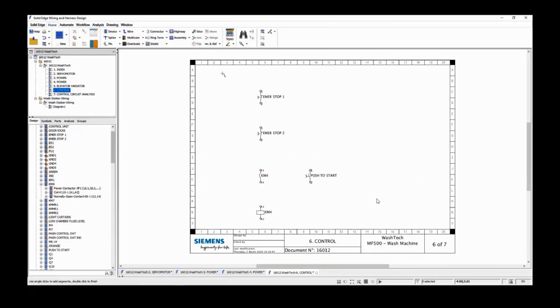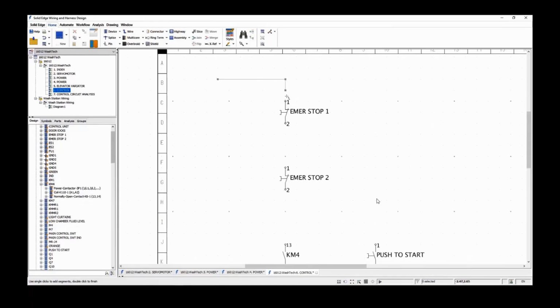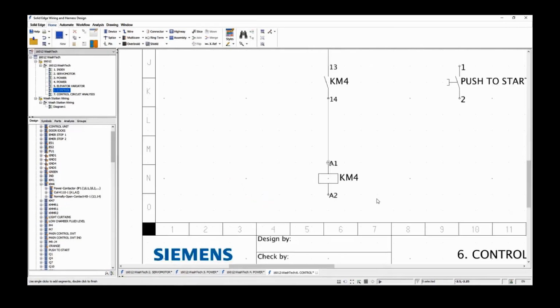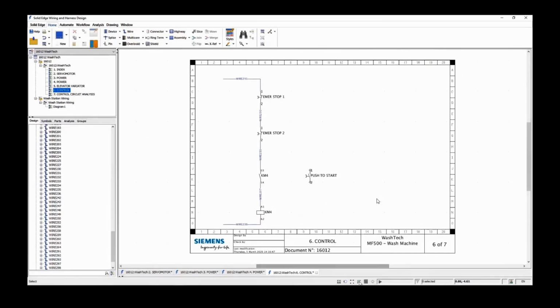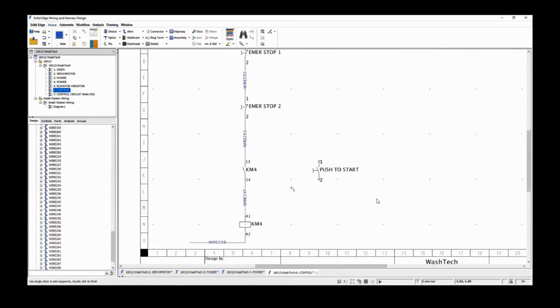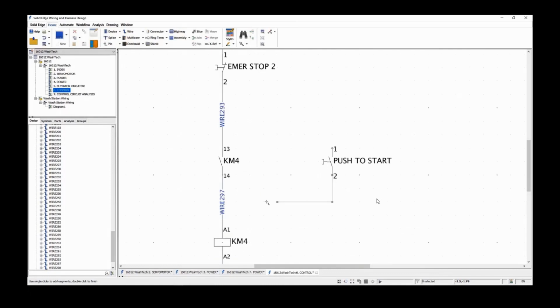Once all the naming is done, we start the wiring. A simple add wire and select the connect points on the devices adds the intelligent wires. Finally, we'll add the wires for the switch and chamfer the wires to indicate which contact it's wired to.